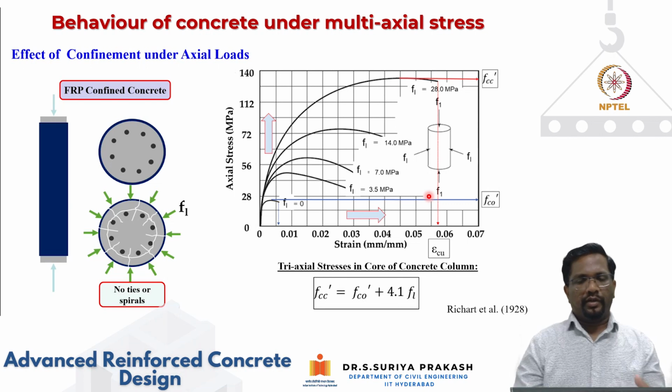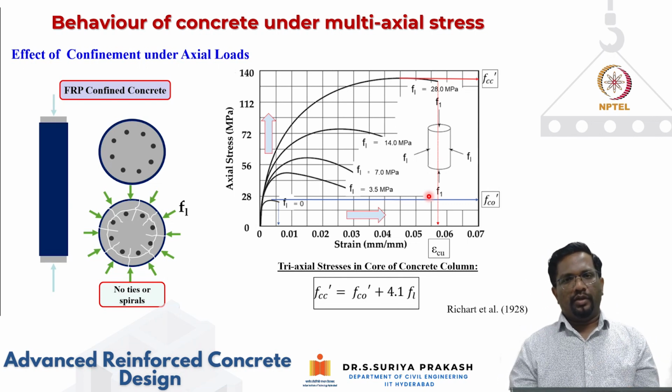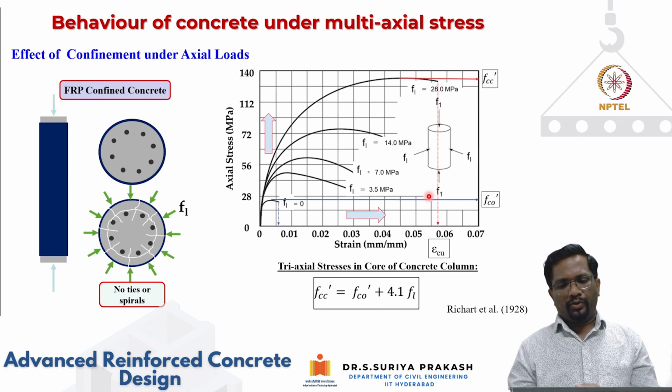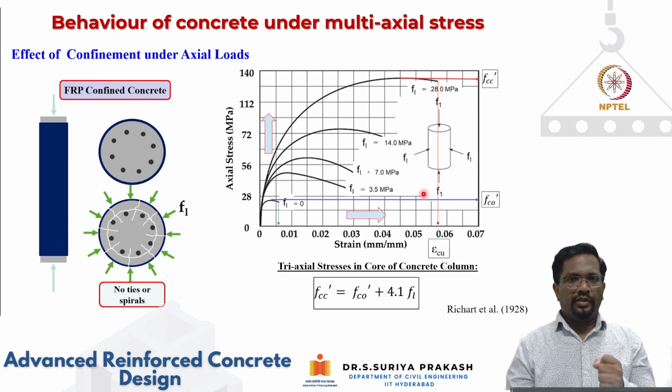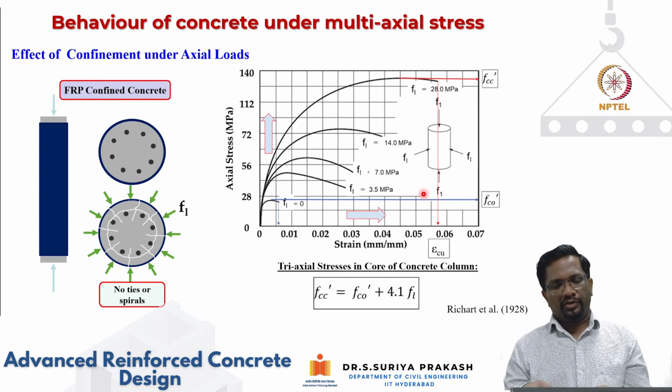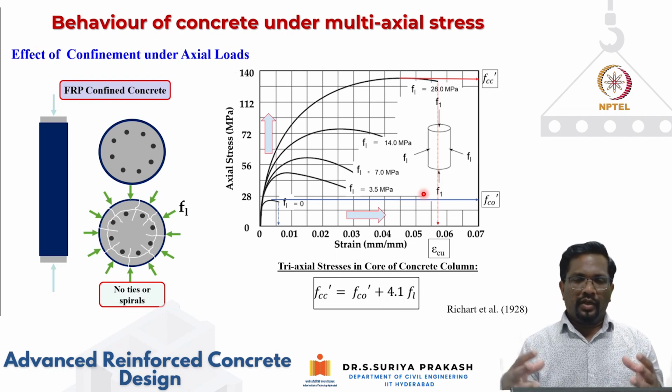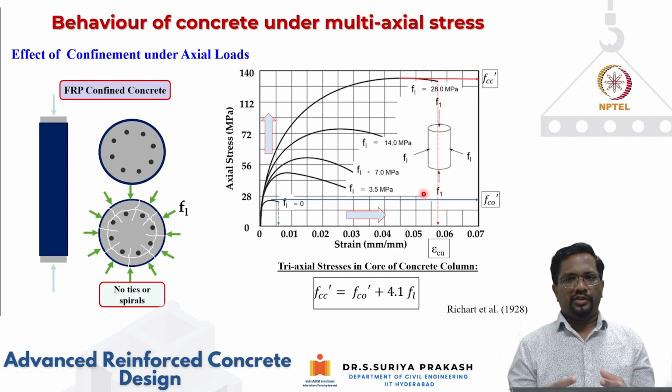In fact, in reinforced concrete column design in the module, we will talk about that. Precisely the role of the transverse reinforcement is to put the concrete core under this kind of triaxial compression stress state. So you generate confinement.